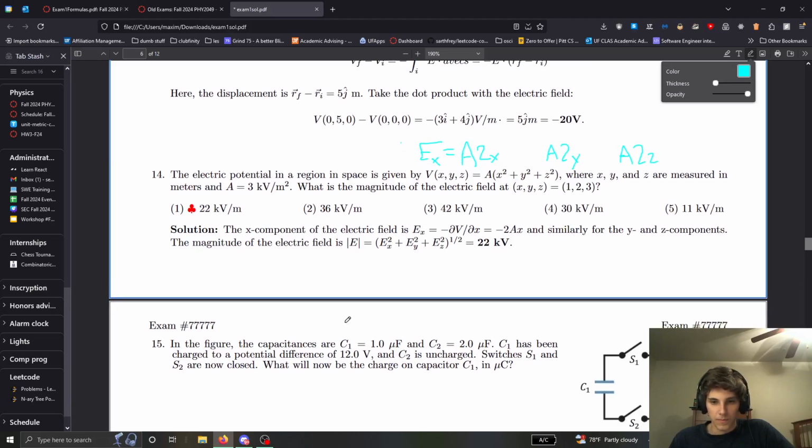This problem, it's weird. It seems hard, it's not as hard as you might think. So basically you have a capacitor here, one of them's loaded up like so, one of them does not have any voltage. Important thing to note, they give you this voltage. These are coulombs where you label them as plus or minus charges. The coulombs are equal to the voltage times the farads. Basically, the capacitance. This is annoying. The charge is equal to the voltage times the capacitance. And since this is 1, you just multiply them, and it's going to be plus or minus 12.